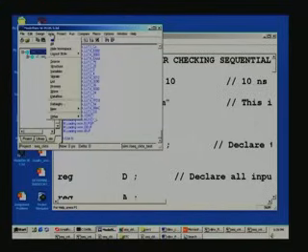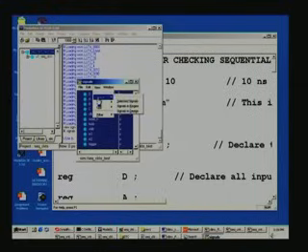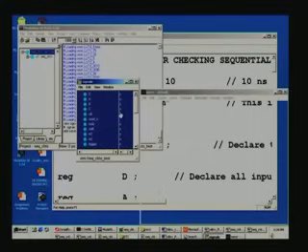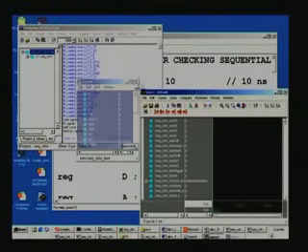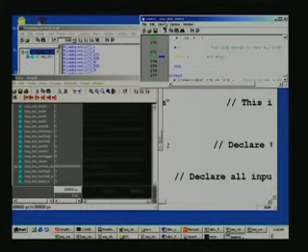In order to see that, click view, then signals, then again view, then wave, then the final last option, signals in design. So, it has opened the wave file, you do not require the signals anymore, and if you click on this it will run. So, it has run and stopped, and as usual the source file is opened at stop at terminated. So, you do not require this.